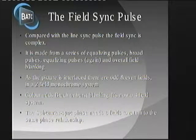Right, now the field synchronizing pulse is much more complex than the line synchronizing pulse. It's made out of bits and pieces. A simple cheapo camera will just have one single broad pulse and it'll cross its fingers and hope it's right. But professionally, it's made out of equalizing pulses, broad pulses, and some more equalizing pulses, and the whole thing is encompassed in field blanking.